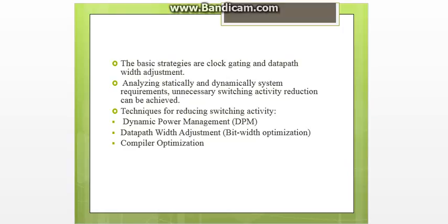Next is the dynamic approach, which controls the active data path width. This approach is called value-based clock gating. The basic mechanism to reduce power consumption is operand value-based clock gating to turn off portions of memory, buses and arithmetic units that will be unused by narrow width operations. This optimization results in around 50% reductions in the data bus and integer unit power consumption. By applying this to data memory, 80% power reduction can be achieved.